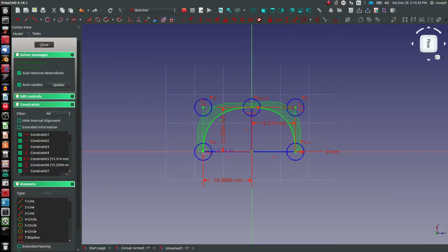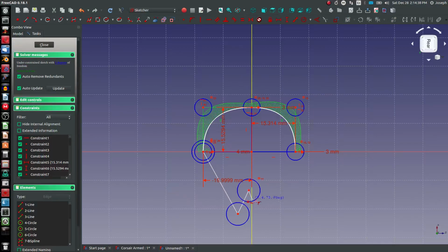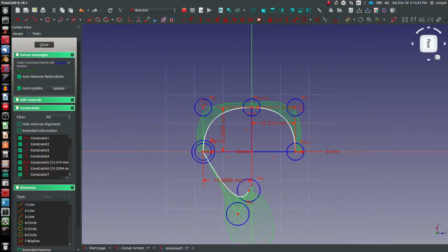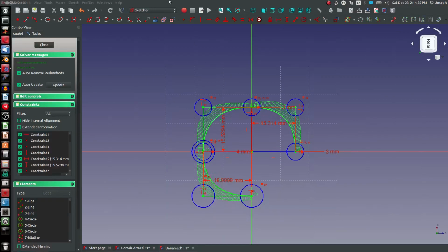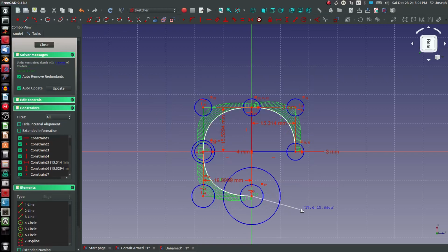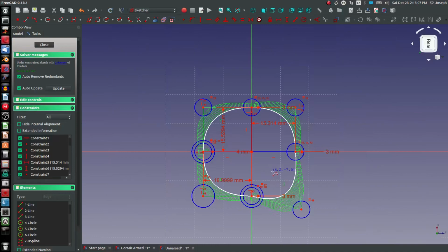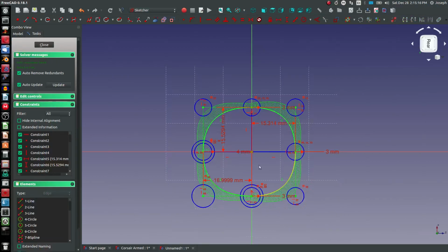I'm simply going to manually do the other side, and I can use a symmetric across my origin to properly position that point. And choose vertical. I like doing it manual because I know that it turns out exactly that I want it to. Horizontal, exactly the way that I want it to. Now, oh, and that did not latch on, I could see that, so we're going to highlight there and there, and that looks like it worked. Vertical, again using the V and H keys, H for horizontal.